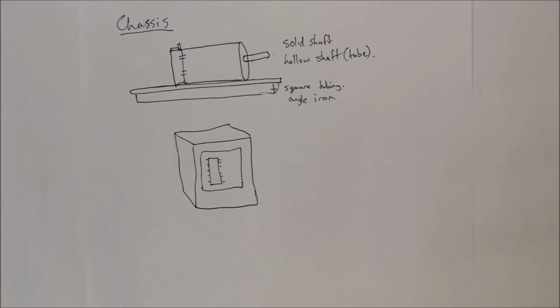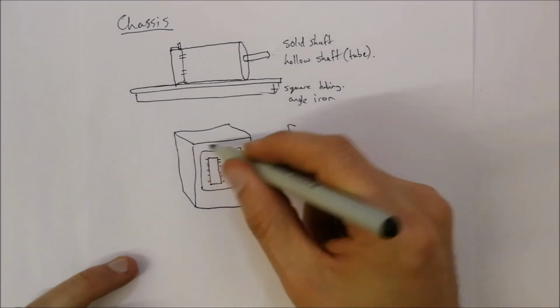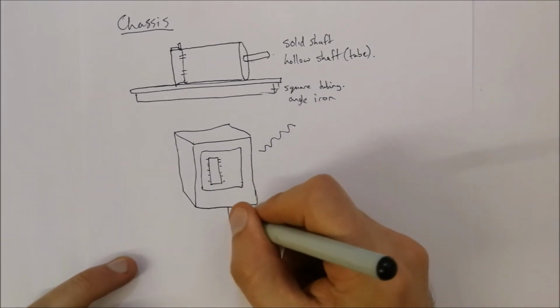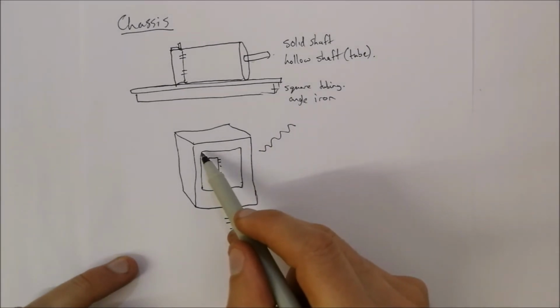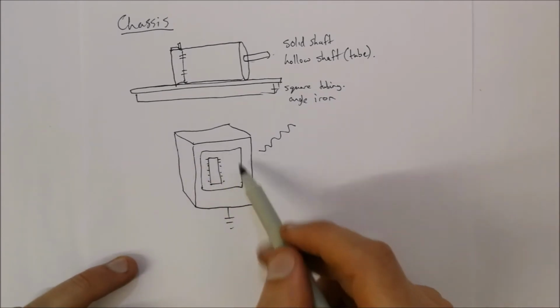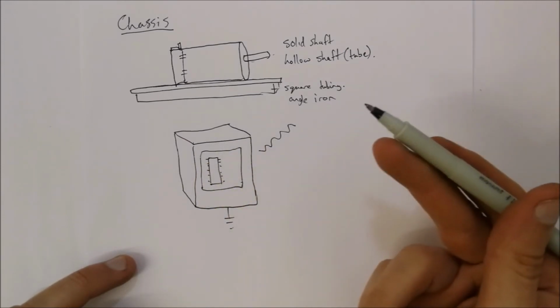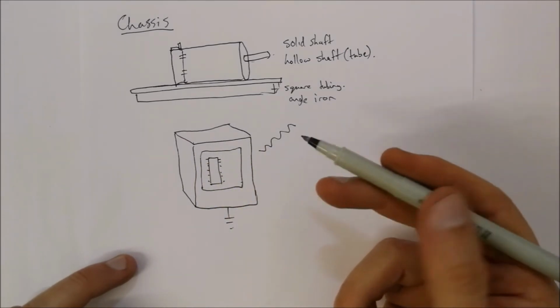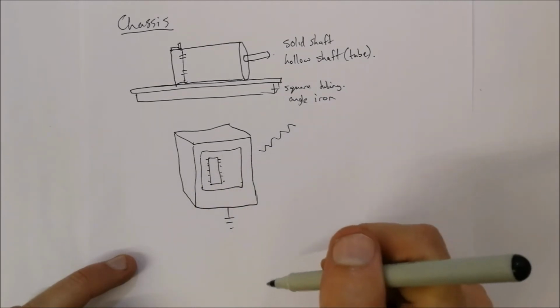And to prevent interference from signals coming from outside, you need to shield this off and ground this whole box. So what you could do is have a plastic box for the electronics itself, and then place this whole electronic box inside of a metal box. But again, so much work, not much forces acting onto these specific boxes.